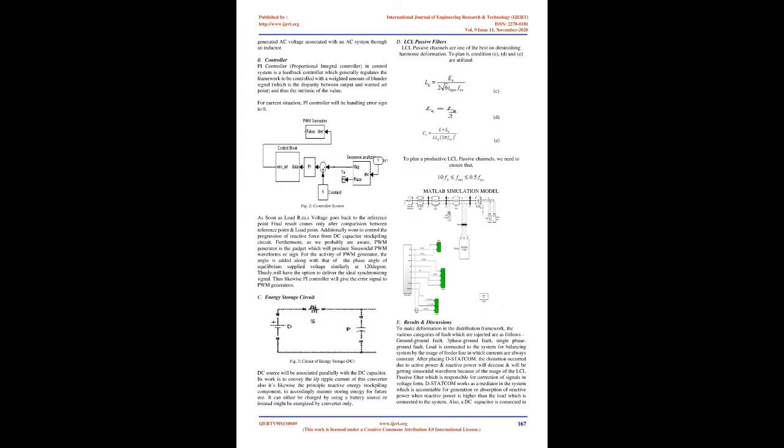If the output voltage of the VSC lags behind the system voltage, then the inverter will absorb real power from the AC system to charge the capacitor. Whereas if the VSC output voltage leads the system voltage, then the real power from the DC source or capacitor will be supplied to the AC system so as to regulate the system voltage to 1 p.u. or otherwise again make the capacitor voltage constant.